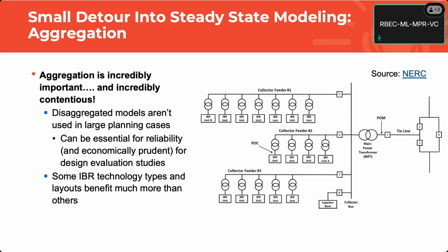And the positive sequence phasor domain is where this is important. You do not need to do EMT at all in a disaggregate. You may not even be able to, and the things we're looking for aren't able to be studied. The only caveat would be power quality and harmonics, which is another thing. But that's a special study, yeah.